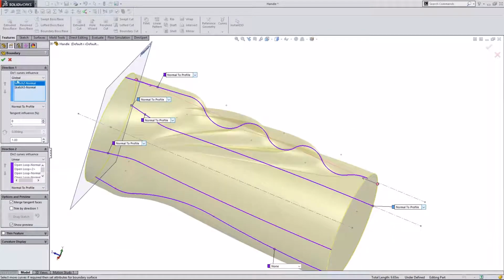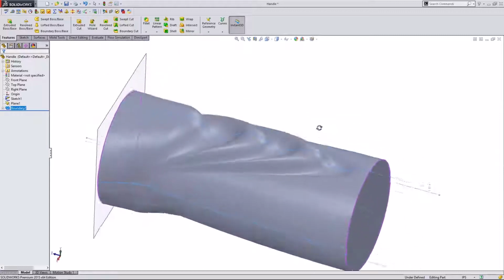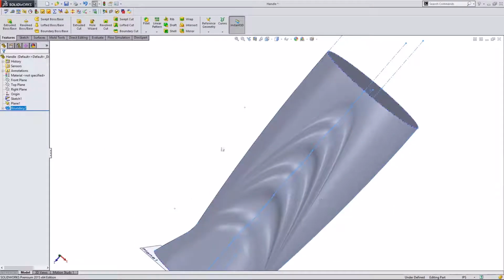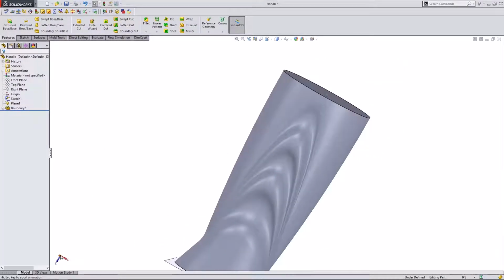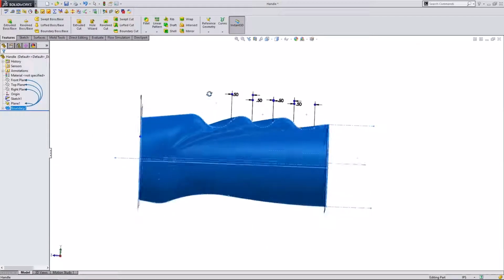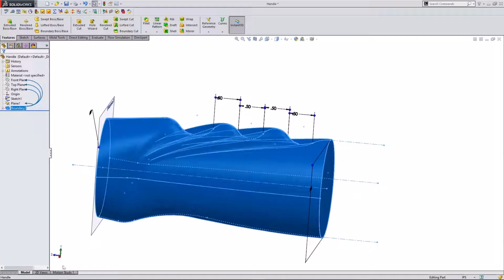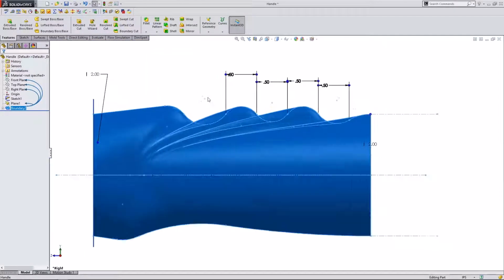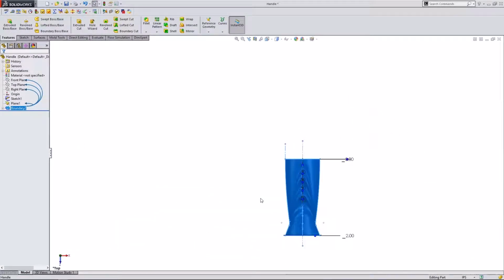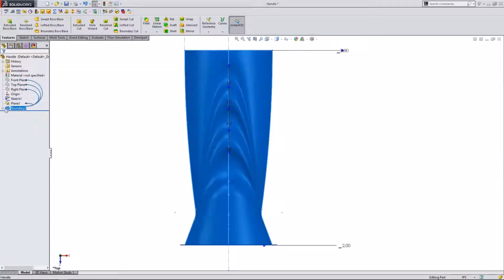And this is really just something that happens in SolidWorks. So you can see that the material is really stretched. This is really not a good situation to be in. And I believe it's partially because of the fact that this profile for the boundary surface, it's really only on one side. So there's not much balance, and that's causing the material to sort of stretch a lot more than it needs to. And this is really, like I mentioned, something that happens a lot in SolidWorks when you're designing a part. It's just something that needs to be worked out over time.